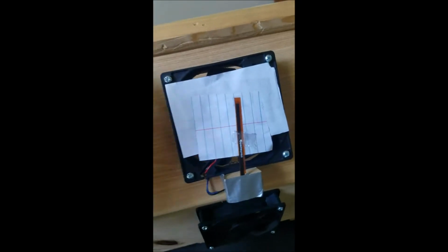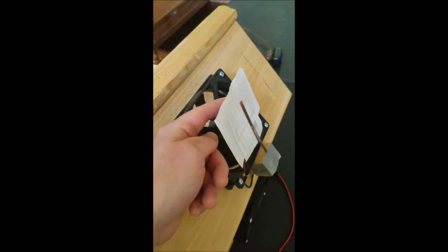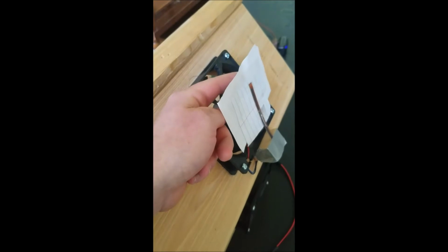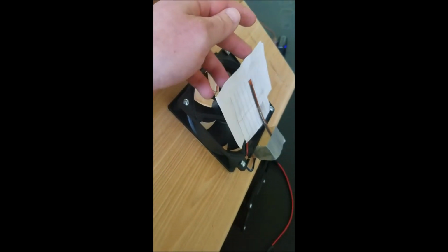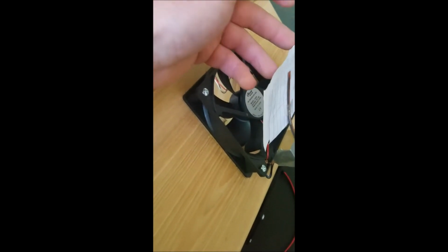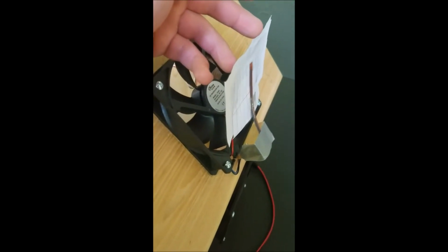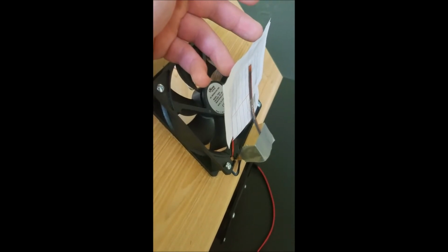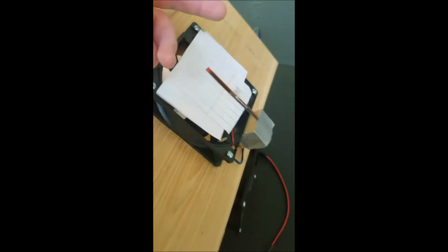The sensors that we are using are flex sensors. It takes the voltage and we converted that to an angle. And after we converted to angles, we were able to see what the maximum airflow of the fan is, which is displayed on its data sheet, and calculate how much of an angle is given to the maximum airflow.